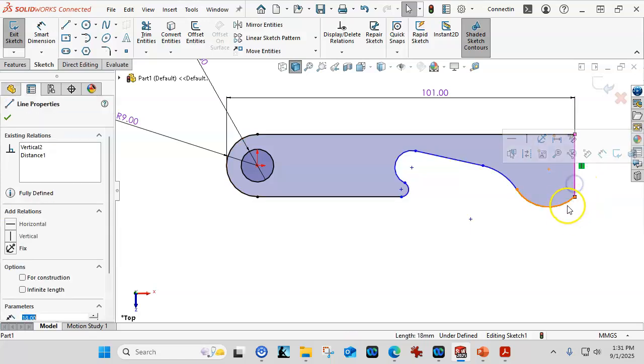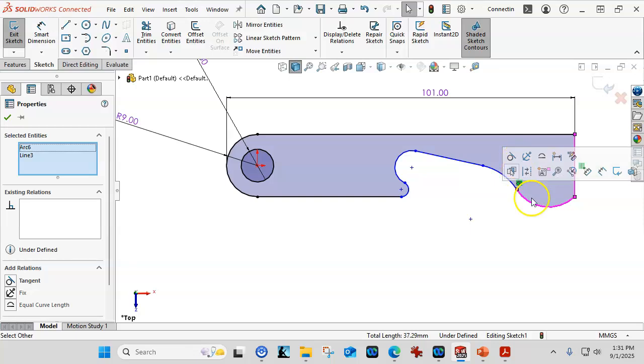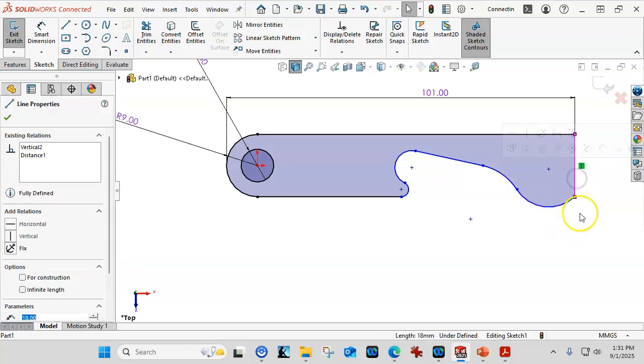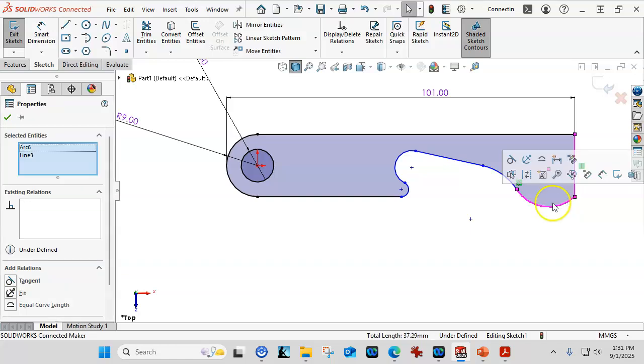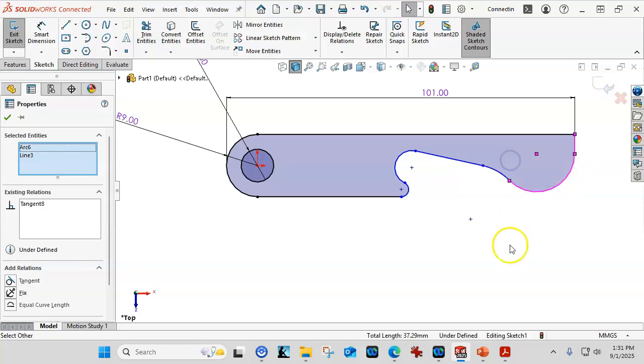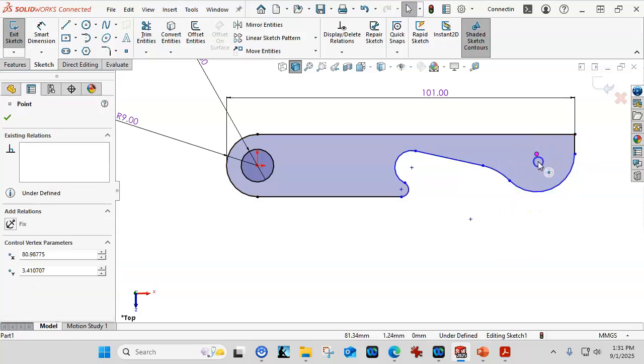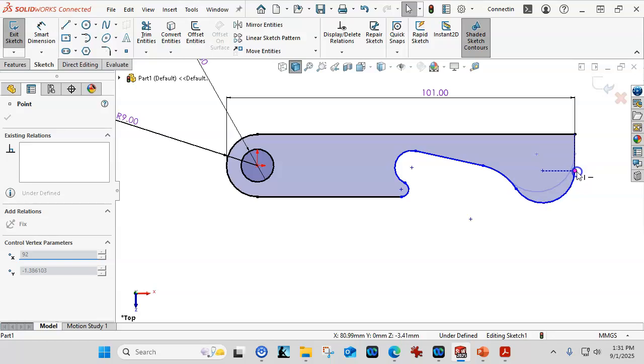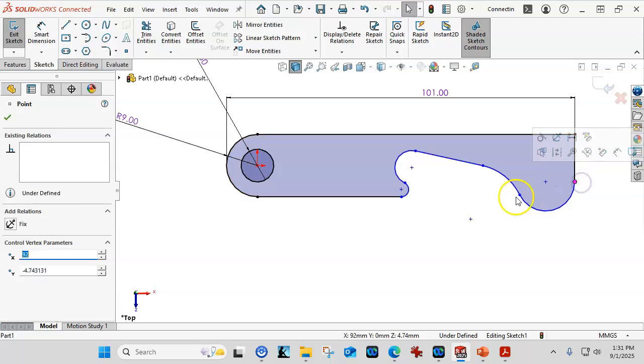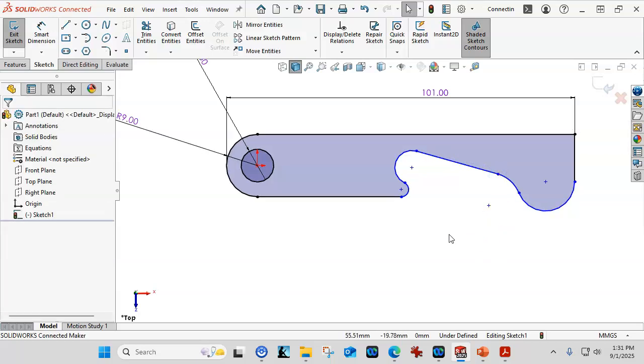So when I change this over to tangent, again, highlight the first item, hold down the control button, highlight the second line, second arc or object, I can go to make tangent, and now that becomes smooth. It pulled it up a little bit further than I would have liked, but we can grab one of the endpoints, one of our objects, and let's just say, massage that into place.